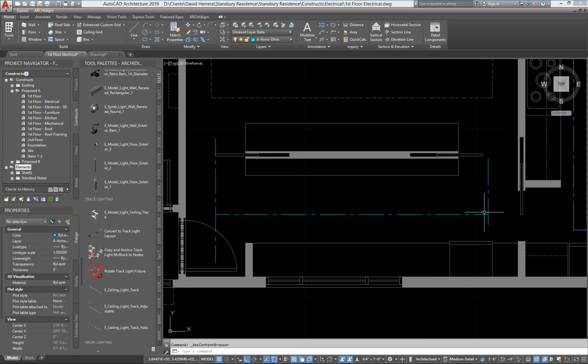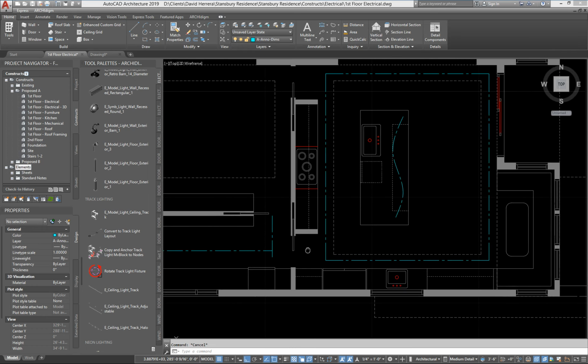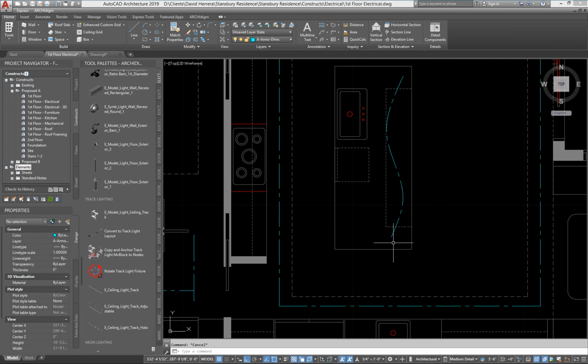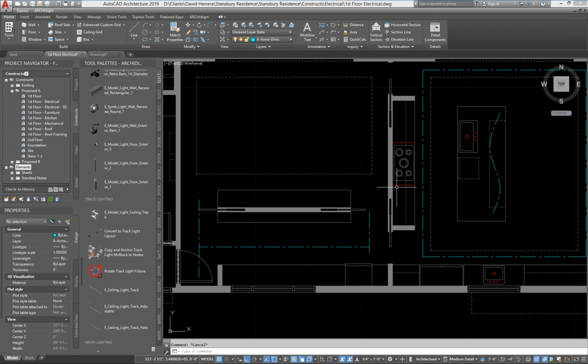So here, in this one area that I'm zooming into, there's a need for a set of recessed cans down this hallway in a kitchenette area. And what I want to do is I want the center line to be centered on this doorway, and then also centered on these two other doorways. So I want my first symbol here, and then a set of cans along here, laid out as evenly as possible within the limitations of the framing, of course. And then over here in the kitchen area, there is a soffit area, so I want some ceiling cans around there. And then we'll just take a look at a fun one here where I just put a spline object in to show you how layout curves are not limited to just straight lines.